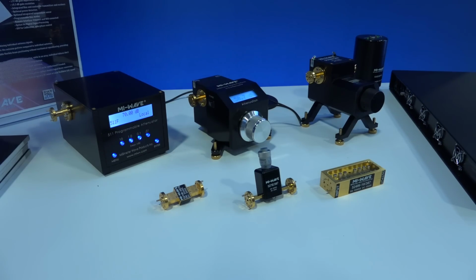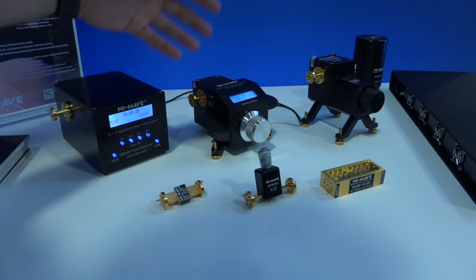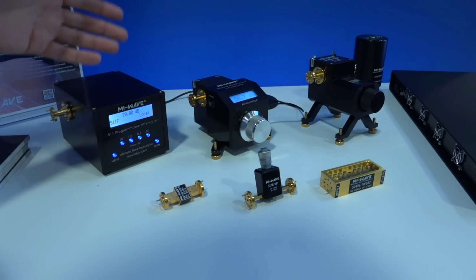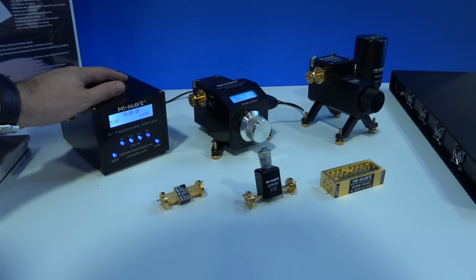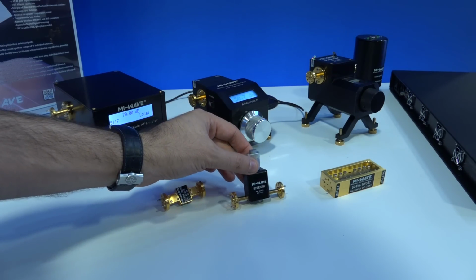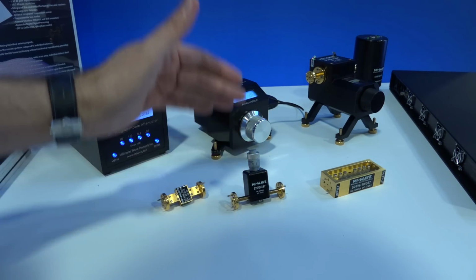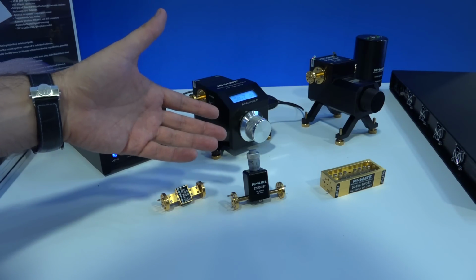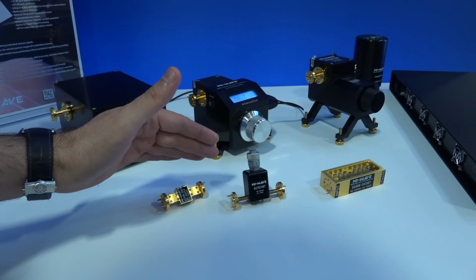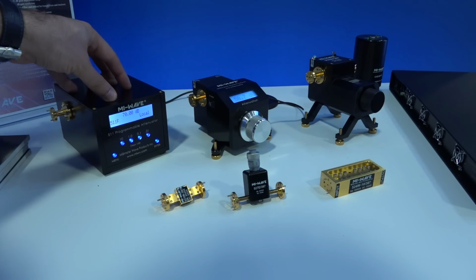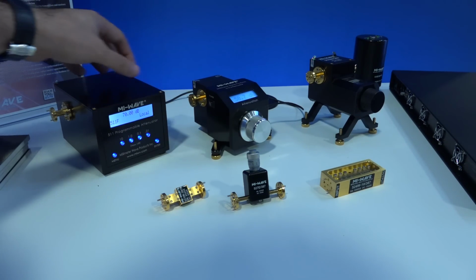So here a few new products from MiWave. We do have a few different versions of these attenuators. Now in a waveguide setup, to be able to have a predictable attenuation is actually quite difficult, and the reason is because all of these micrometer-based attenuators do not have a linear range of attenuation with the depth of the micrometer, and so you have to have some correction. You have to pre-calibrate this, know exactly where you are in the depth, and then that will be your attenuation. The nice thing is that in this unit, they've done that, and they've done that to 0.01 dB of step.